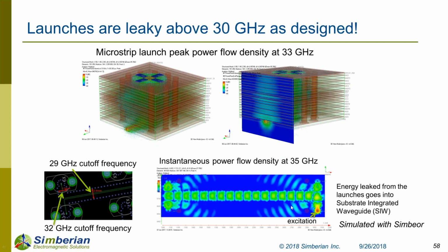Yeah, 16 vias per launch sounds like a horror story, but that's why, if you want 112 gigabit per second PAM4, that's a millimeter wave. The simulation has to correlate to measurements up to 80-something gigahertz. Think about it. That's quite a challenge.